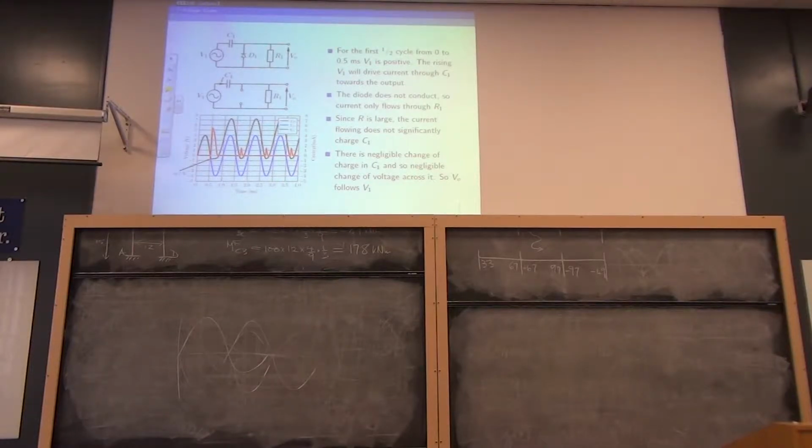So what we've really got is a high pass filter. It doesn't help to think about it like that, but it is the same set of components, laid out in the same way. And since we're making the value of the resistor quite large, the current that flows is not very significant. And that current does not charge up C1. So the same voltage appears here as appears here, is what we're saying.